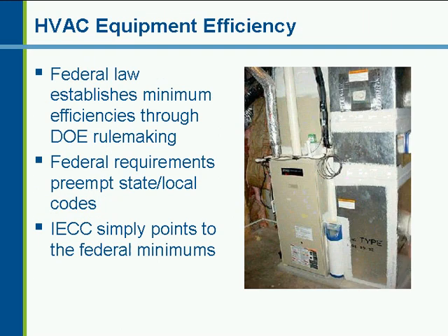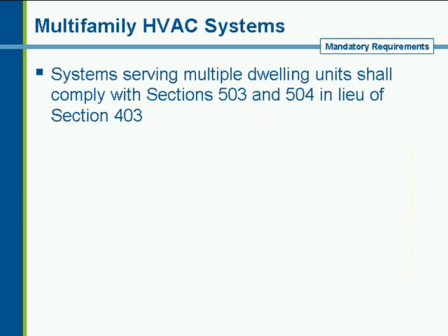For multifamily applications, if you have systems that serve multiple dwelling units rather than a separate system for each dwelling unit, you're not subject to the residential chapter of the IECC. You must comply through the relevant sections of the commercial chapter, 503 and 504.